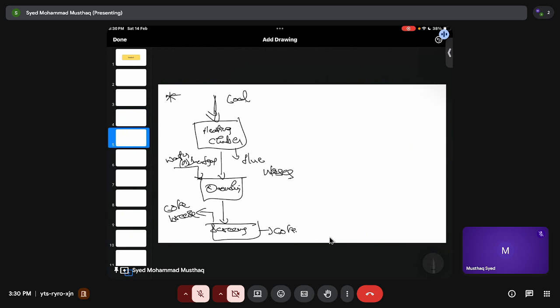Now we are only considering the coke part, okay? So let's worry about the other thing. At first you will have quenching. Once you have done the coking process, you do the quenching. That means you add water or inert gases, then you cool it down, then you do the screening for your next process, whether it is iron making or coke making, okay? In iron making it is your primary fuel, in coke making it will be your secondary fuel, right?